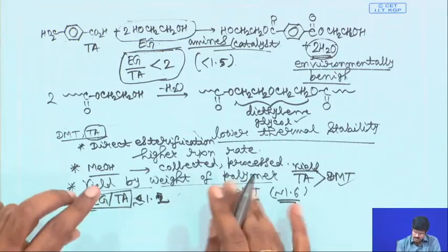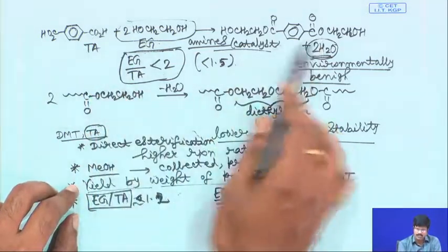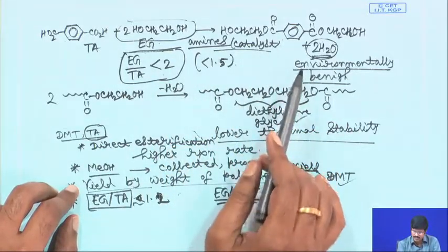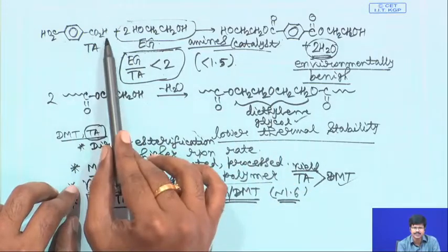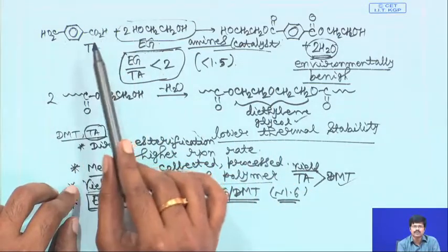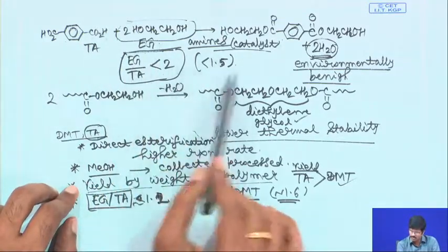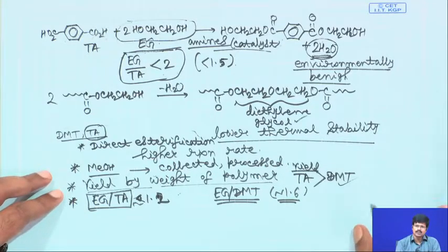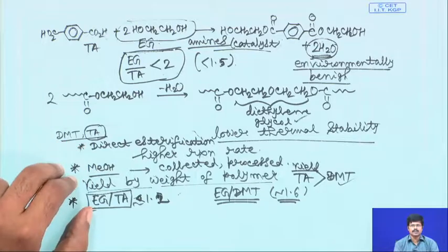And also, you do not need any trans-esterification catalyst for this particular reaction. Of course, you can use some catalysts, but without catalyst it will also work, because you have carboxylic acid present, and the carboxylic acid can self catalyze the reaction. So, you may not want to use a catalyst, if you want to reduce the expense. So, these are the advantages of the terephthalic acid route over the DMT process.